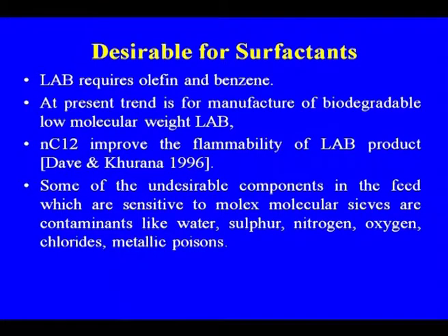Some of the undesirable components in the feed which are sensitive to the molecular sieves are contaminants like water, sulfur, nitrogen, oxygen, chlorides and metallics. And this is the reason that in the LAB plant also, we do pre-treatment of the feed which is going to the Molex process.